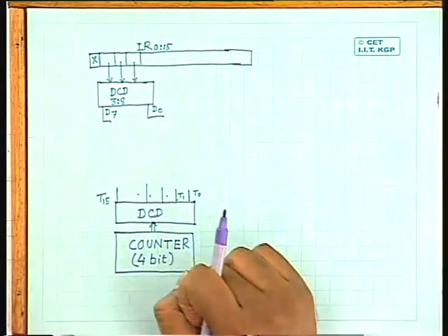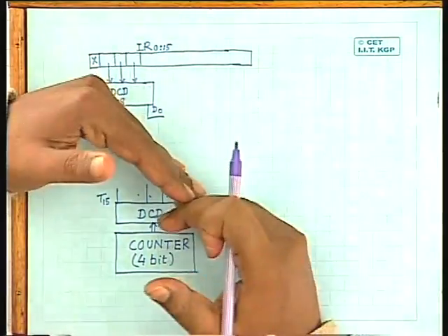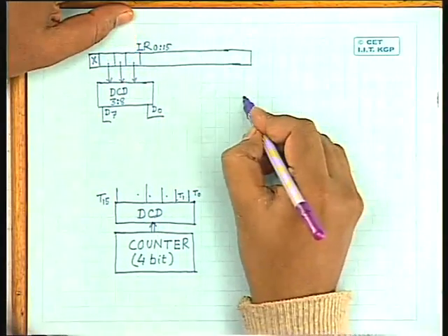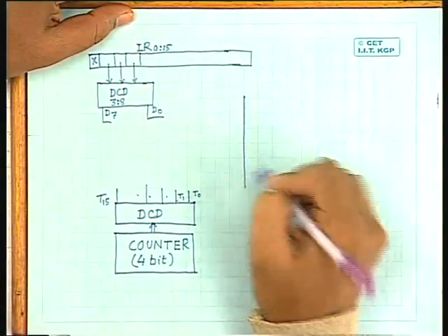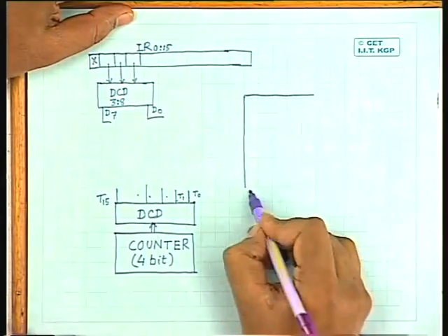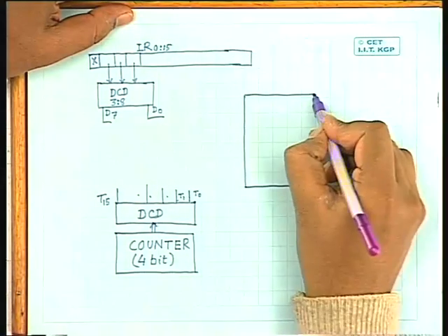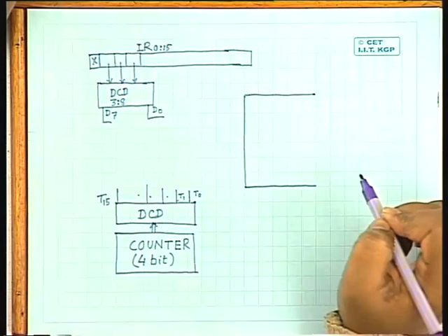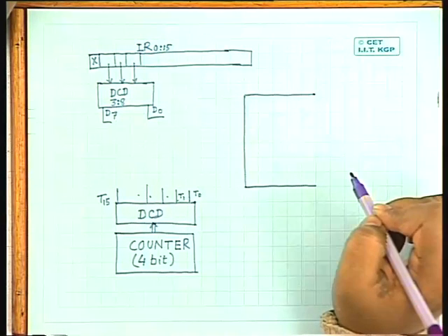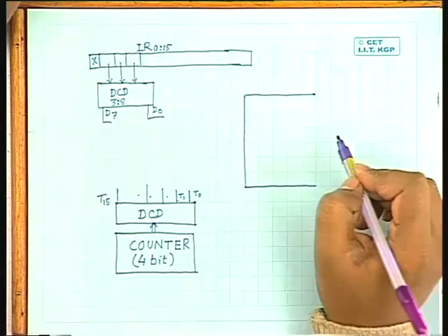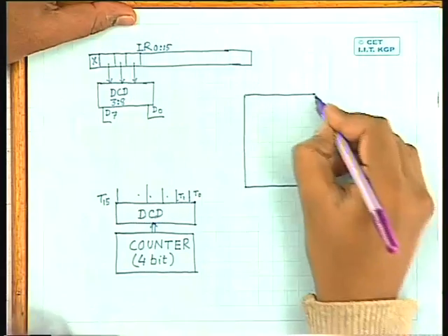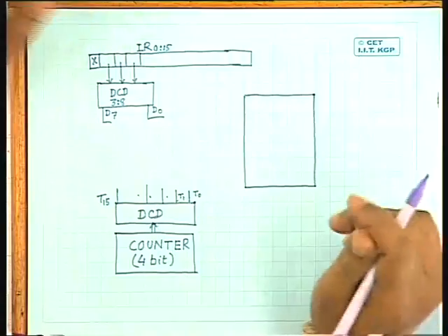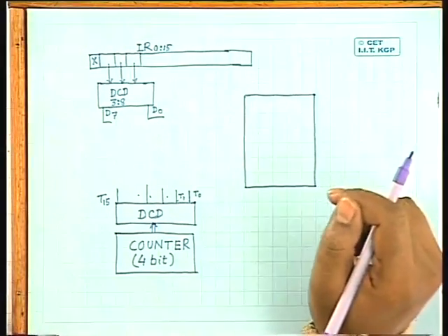What do I have to do next? I have to combine these two to generate the control signals. That means the timing and control circuit. Not just those two, those 3. You require the other opcode bits also, like using the rest, 0 to 11, for register reference instructions. Yeah, that is true. And what's the input to the counter?